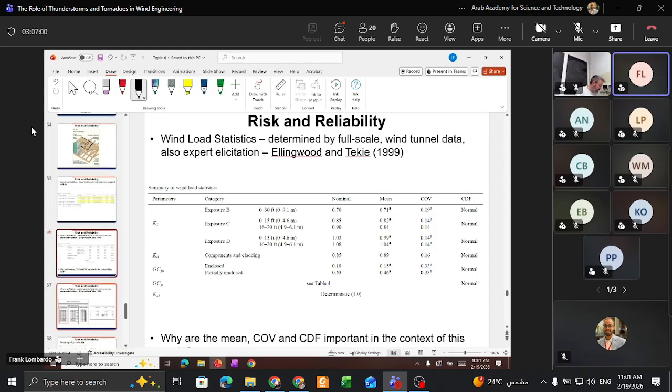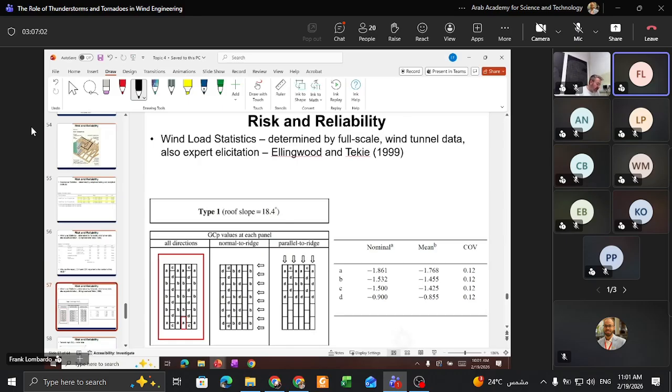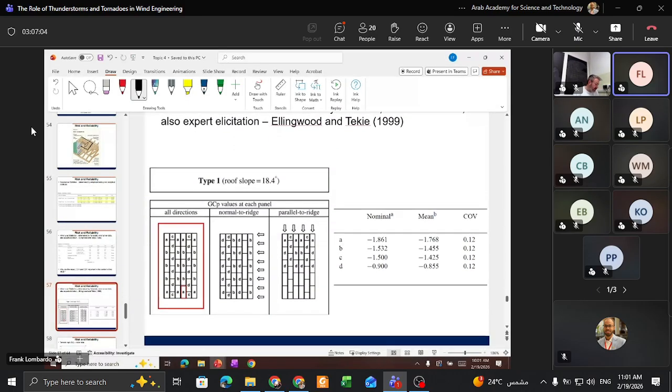And then the second one, as you know, that pressure coefficient is obviously going to vary depending on the position on the building. So that Cp is higher in the roof corners, for example, roof edges. It's less negative on the roof when we're considering different locations.